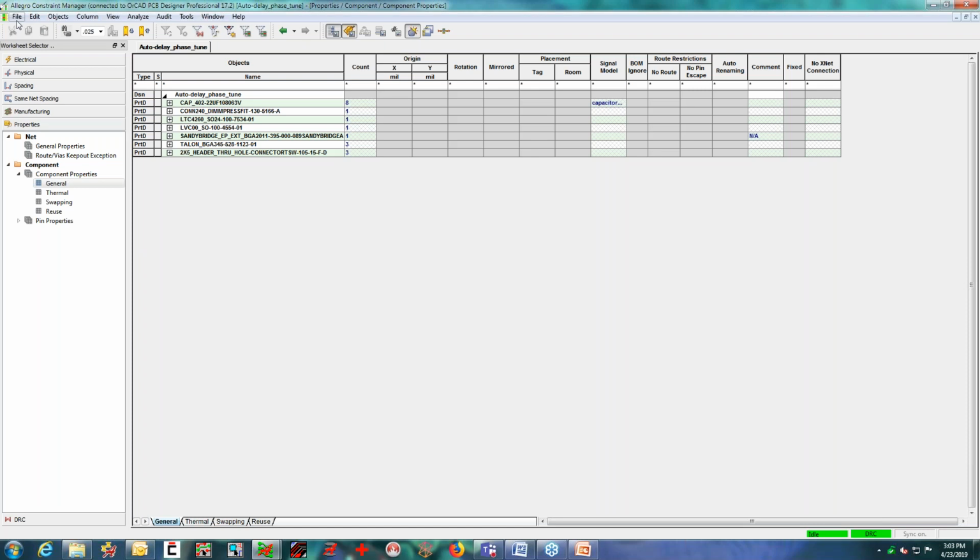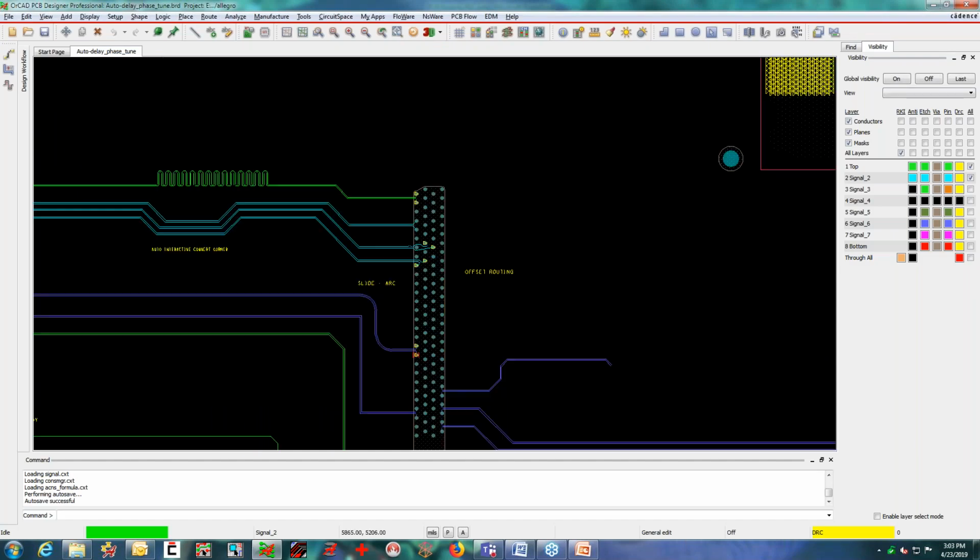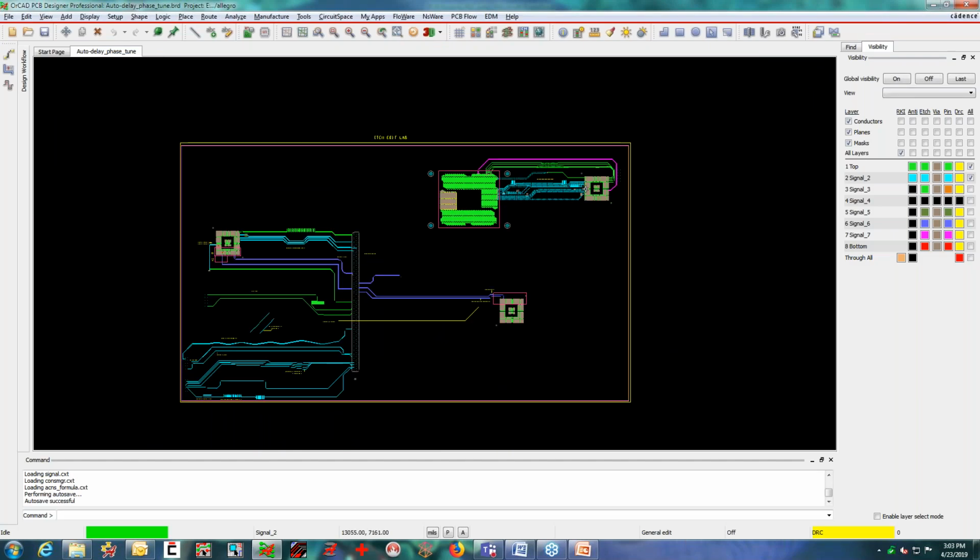known design violations that occur. For example, you might have a connector that overhangs the edge of the board. Now in this case I don't have one on this board, but you might have a connector that overhangs the edge because that's by design, right? Well, if it crosses my component keep-in, of course that will show up as a violation. So I would waive any of those known DRC conditions to get them out of the main DRC list, because what I'm trying to prevent is when I look at my regular DRC report, I want to make sure that I'm only looking at real problems.